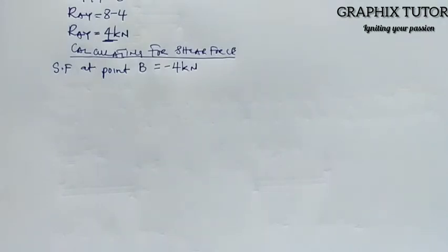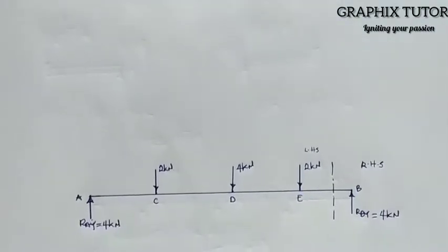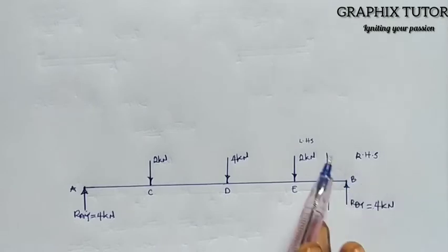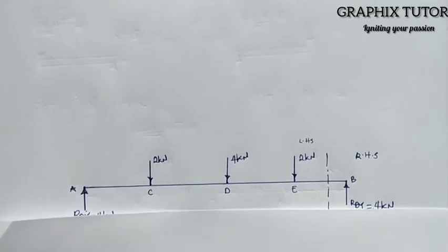Now, similarly, we can also get the same thing here. We say the shear force at the right hand side facing up, we're having -4, right? And the definition for shear force is that the algebraic sum of all forces acting either to the left or to the right of the section. So to the right of the section we're having -4, and let's see to the left of the section if we have -4. You don't have to do both of them, you just choose one part. But to prove some things right to you here, let's see.